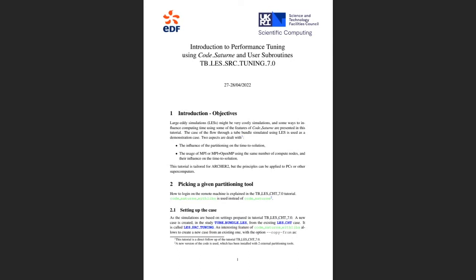Assuming you got the file, this tutorial is a little bit different because we are going to use user subroutines to use different partitioners and to run a very small simulation, a short simulation of the case you were running yesterday, for just 100 time steps, to see if there's any influence on the time to solution depending on the partitioner you're using.